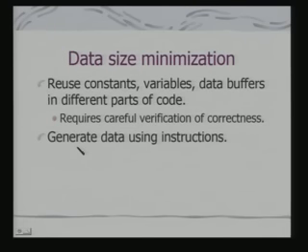The other strategy followed in many of these embedded systems is that you generate data using instructions. That means you get a task node for generating data using instructions. Okay. So, if you need some special kinds of instructions for an application, try to model the data using instructions. What is the advantage? The instructions would occupy less memory. Instructions go into, say for example, flash.